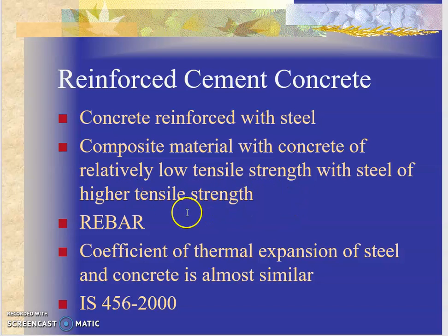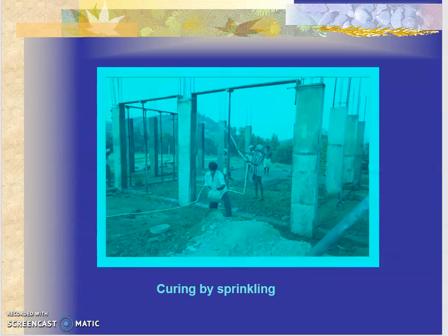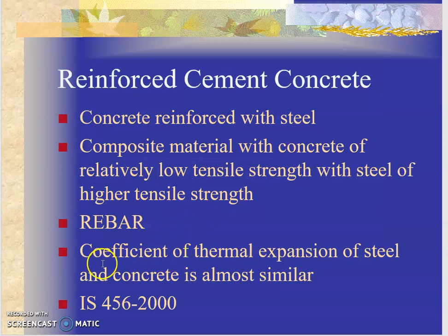At that point, the moment a structure becomes slightly old, let's say around 1 to 3 years have elapsed, you will see hairline cracks where the beam ends, where it rests on the wall. The reason being, both have different thermal coefficients. Both will expand and contract at different temperatures and at different magnitudes. So there will always be such kind of cracks. Now imagine if there are two materials inside one material. Let's say in case of RCC, you have concrete and steel. Both will expand and contract at different temperatures.